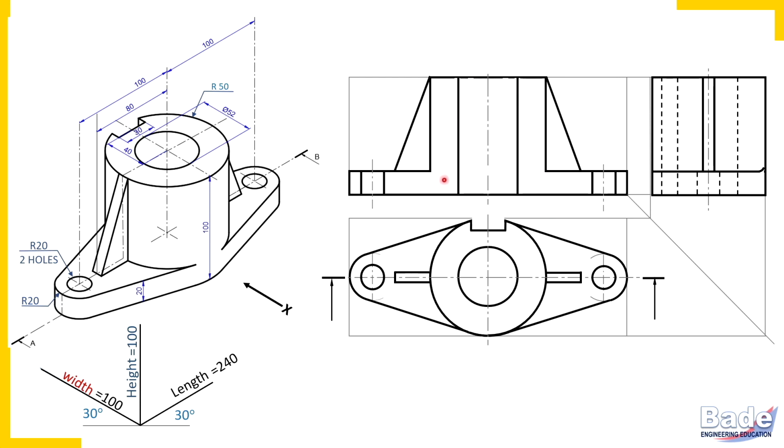Now because of the cutting, new surfaces are getting created. We should draw hatching lines on the surfaces. Now try to understand. This small rectangular surface here, it is newly generated surface. It is portion of the base plate. This L-shaped surface, that is newly generated surface. Now triangular plate here, as I told you, it is assumed uncut. So no hatching lines here.